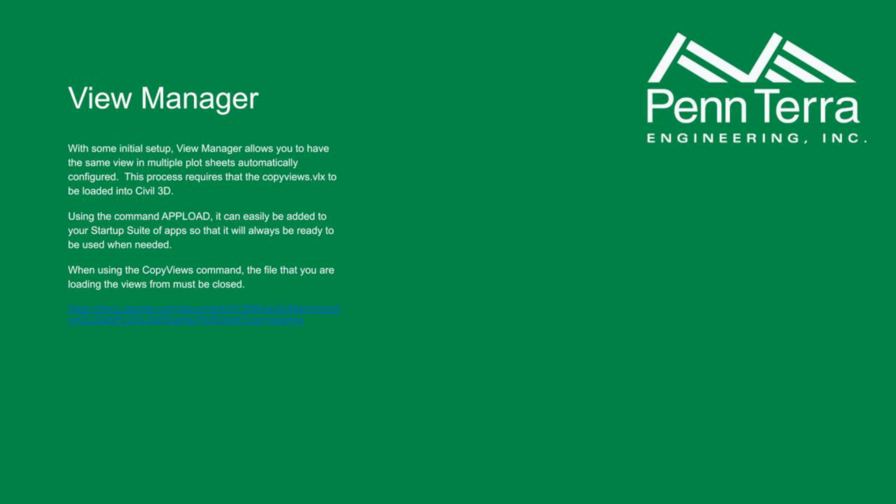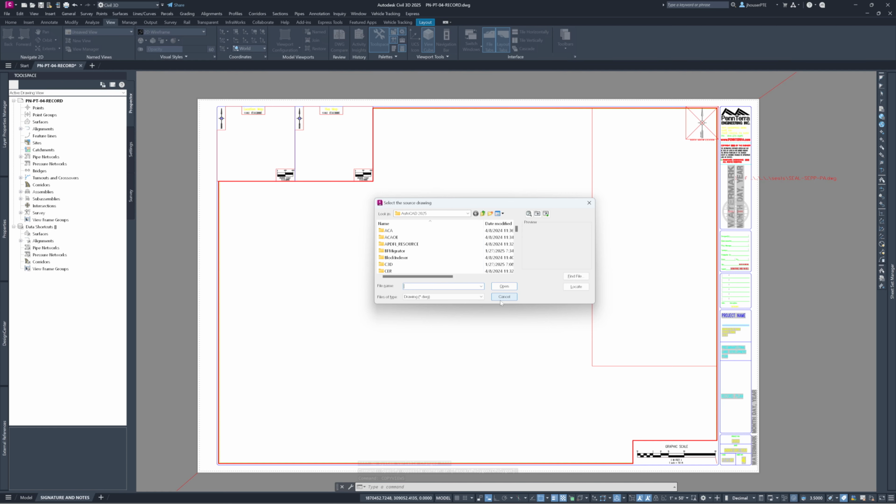All right, so go back to my CAD. At least I remember this time. So right now my MD is open, and that's where I want to get my views from. So I'm going to close that. I'm going to go back into here, make sure that my viewport is not loaded, and I'm going to type in the copy views command. If your copy views command does not come up, I can show you real quickly here.